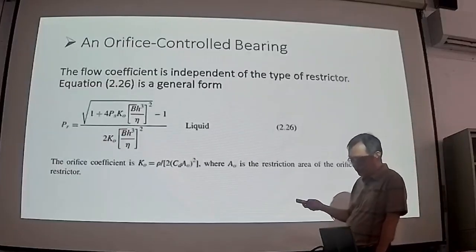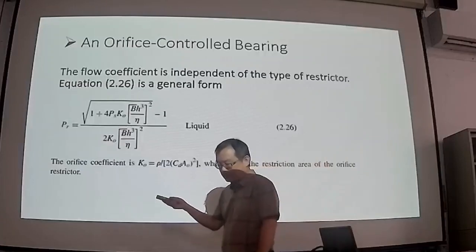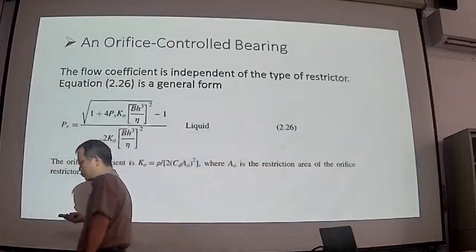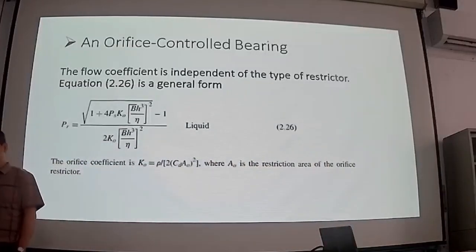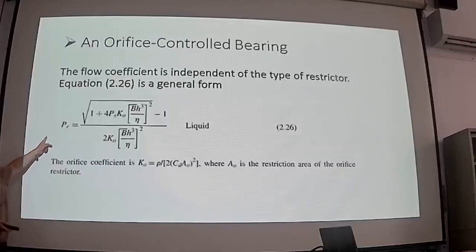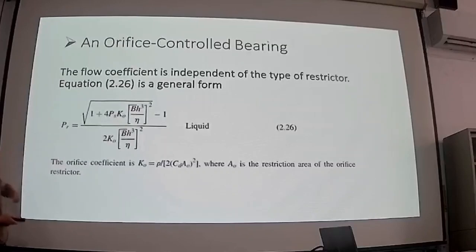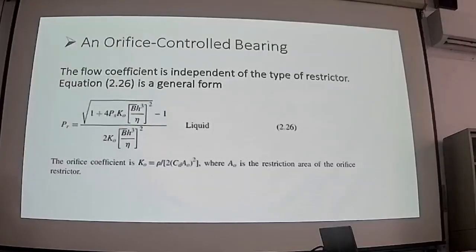We know when the temperature rises, the viscosity of the lubricant will drop dramatically. So in that case, the temperature difference of your lubricant will affect the recess pressure.